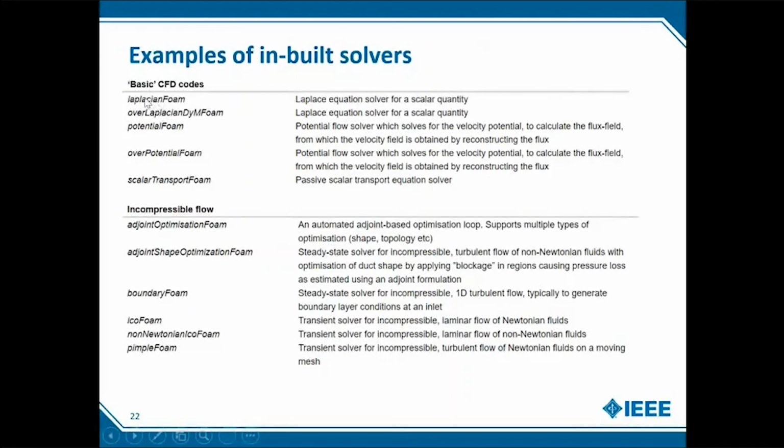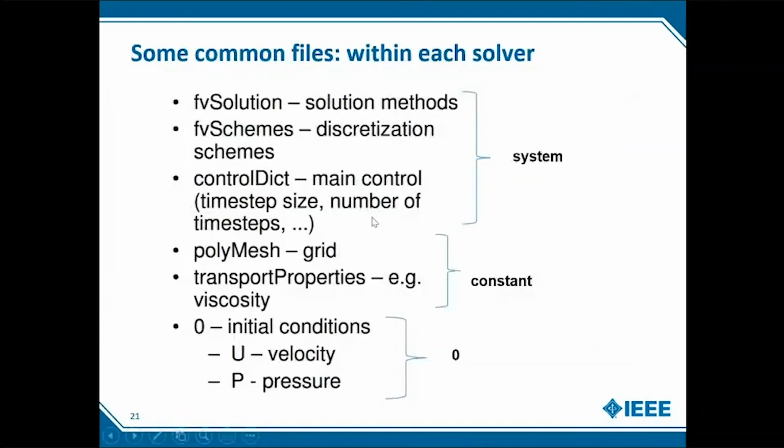And I just wanted to basically show you what is a grid independent study. So basically if you have a computational domain, how do you know what's the optimum number of grids that you have? You can have a very coarse mesh, so that will basically not capture all your physics, or you can have a very very fine mesh that will of course capture all your physics, but it will take a lot of time to run. So therefore there is an optimum number of mesh count.